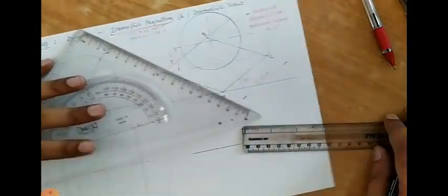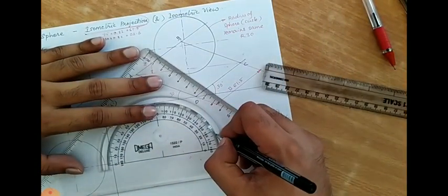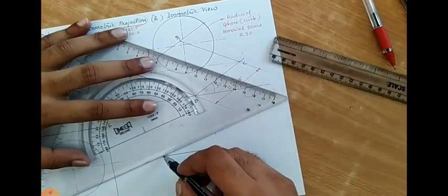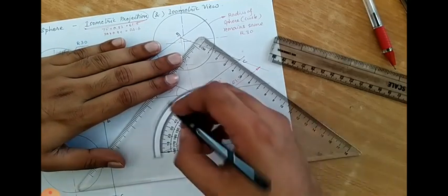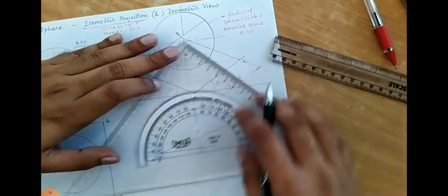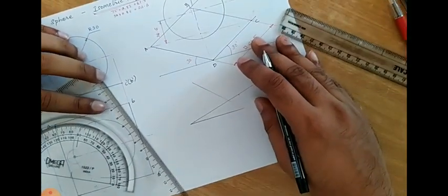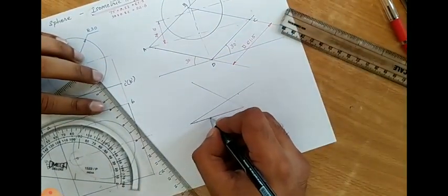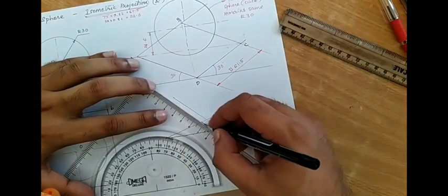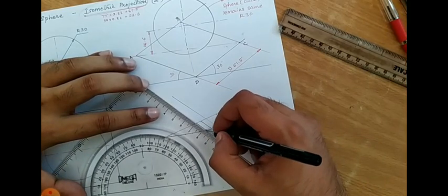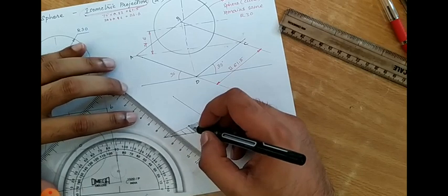And as it is an isometric projection, you have to always show the isometric scale there. In the previous video, we discussed how to draw the isometric scale. Draw a horizontal line, then take an inclination of 15 degrees from one end point, and from the other end point, you have to take a 45 degree inclined line in the opposite direction. The horizontal line drawn now represents the true length. You have to divide the length into equal parts, and to that inclined 45 degree line, you have to draw parallel lines through each division made on the horizontal true length.